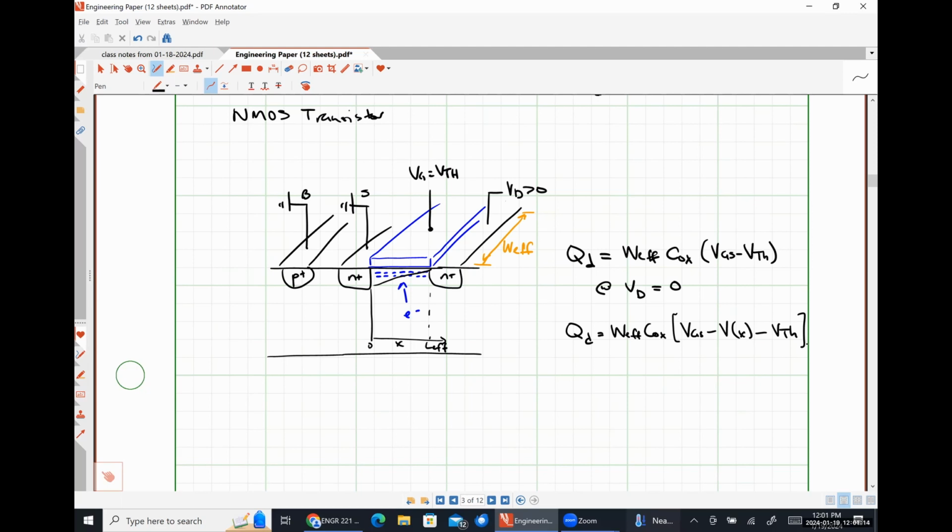I think the short answer is yes. You should have probably done something in your field theory class like that about what happens if you have one plate that is flat and the other plate slightly askew. You can do it by integrating, or you can do it by effectively slicing it into very small capacitors that are connected in parallel, each having a slightly different gap distance, which is actually probably easier than the integration will wind up being.